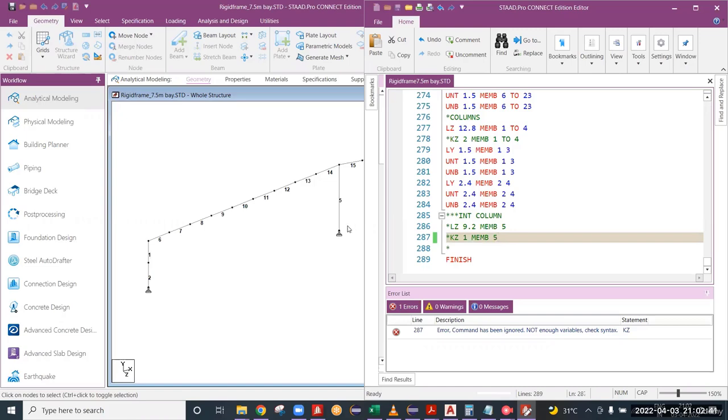And any support comes to this internal column? No, right? Sheeting will be all around the building. There will not be anything internally. If any customer wants partition, that is another thing. If it is any crane that is coming, that time we divide the column. Yes, of course. We can take the unsupported length up to the crane beam. How it will be, I'll tell you.